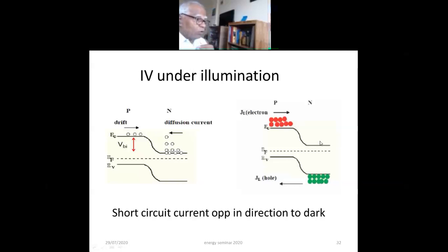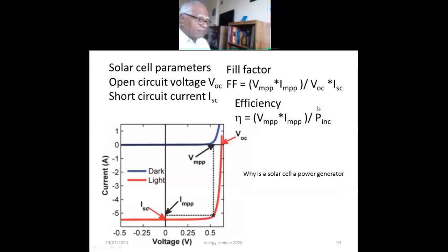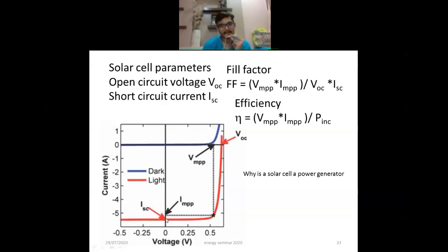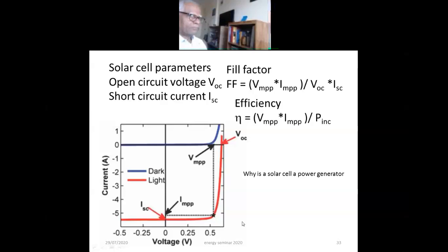Now, when I want to trace the IV, I apply some voltage, a forward voltage, to continue on this curve. Of course, this current and this current add to give me this curve. So this curve is just a superposition of the dark IV plus a constant generation rate. This is not always applicable, but when it is applicable, it's a very powerful tool.